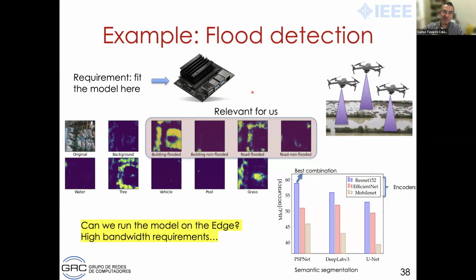And the performance on a UAV is not only in terms of standard AI metrics like accuracy, precision, F1 score, etc., but you also want to see, for example, the frame rate that you can handle for real-time analysis. If you want to process, for example, 60 frames per second and detect objects in real time, it can become a bottleneck. So maybe you have to adjust the flight speed of the UAV to the inference speed of your model running on the UAV so that it accomplishes its mission correctly.